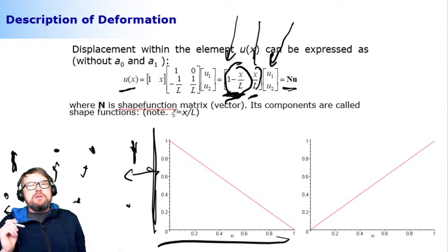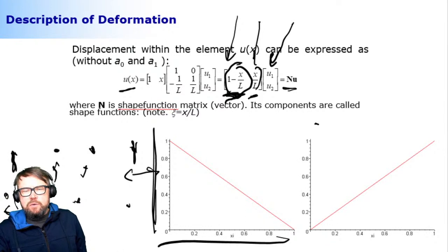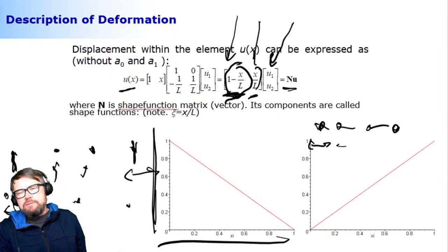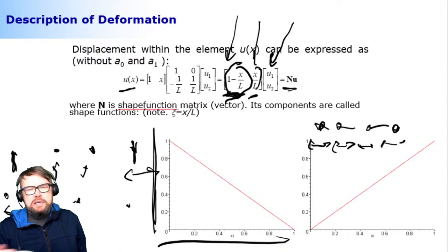Okay, so it's all about polynomials. Everything starts with defining how many nodes you have in a system. You can have boundary nodes. You can have internal nodes as well. Like the example that I explained a bit earlier, I had one internal node. Now, if I have two internal nodes, it would mean that I have 4 degrees of freedom in my system. So I need to select the polynomial such that there are going to be 4 polynomial components.